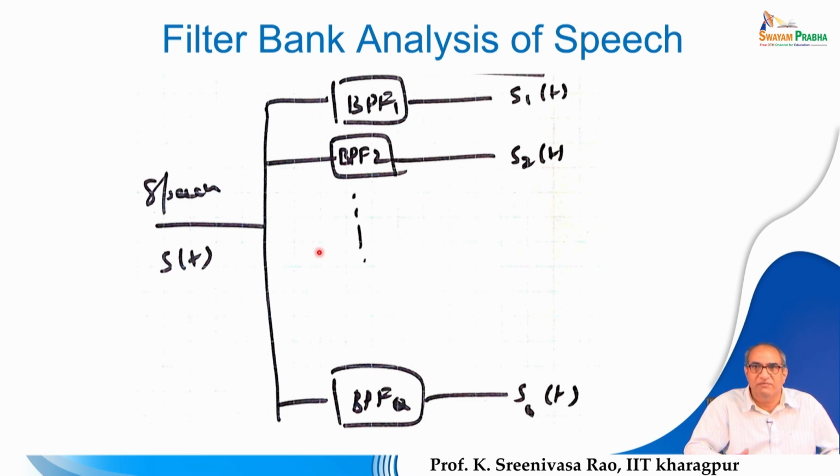And if you want to conserve the bandwidth, you can analyze frequencies up to 4 kilohertz, which is also reasonably good, because most of the speech content, or the energy present in a speech signal, is mostly concentrated below 4 kilohertz or slightly less than 4 kilohertz itself.